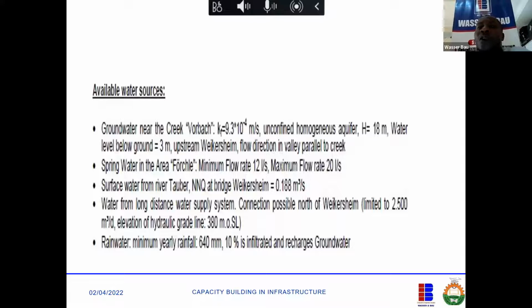And it requires unique treatment processes, okay? It could be nanofiltration methods to treat it. It could be simple filtration using filters. It could be using membrane technology. It could be using ion exchange. It could be using aeration, simple aeration. So there are different methods, but it depends on the constituent parameters that you want to treat.